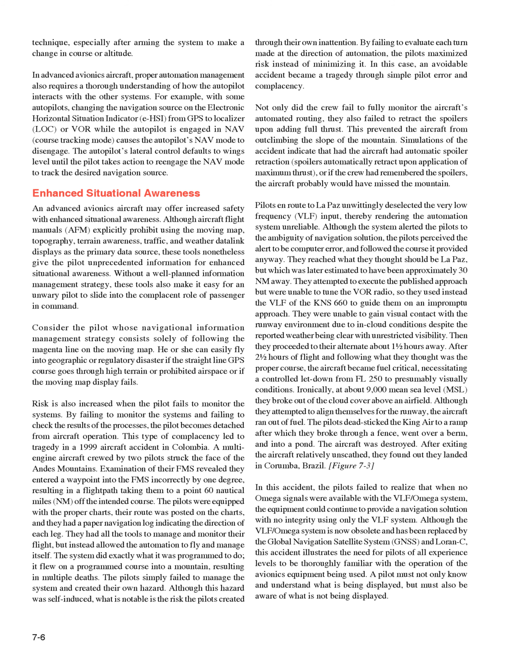A multi-engine aircraft crewed by 2 pilots struck the face of the Andes Mountains. Examination of their FMS revealed they entered a waypoint into the FMS incorrectly by 1 degree, resulting in a flight path taking them to a point 60 nautical miles, nm, off the intended course. The pilots were equipped with the proper charts, their route was posted on the charts, and they had a paper navigation log indicating the direction of each leg.